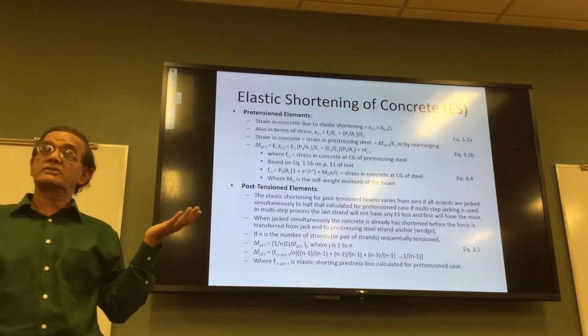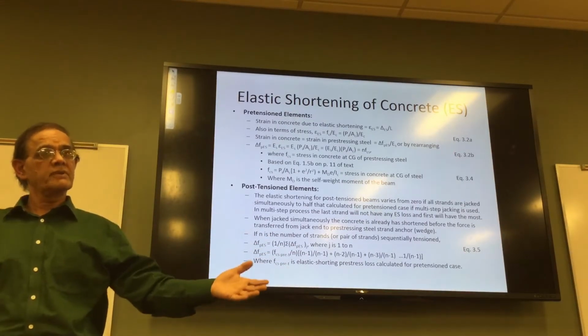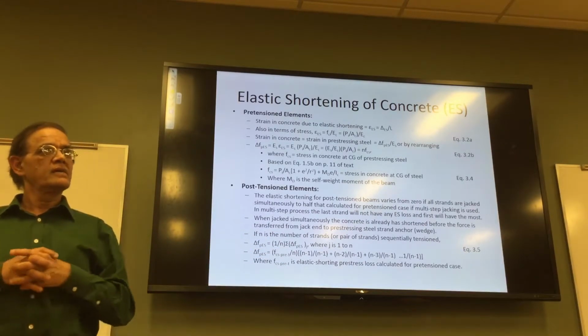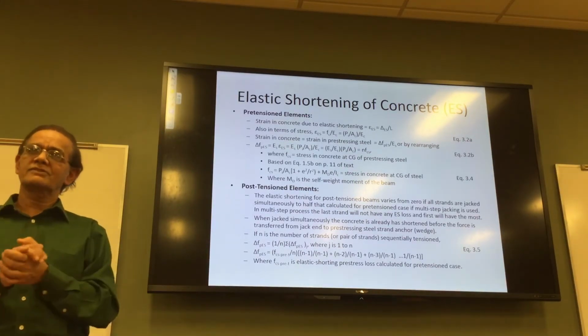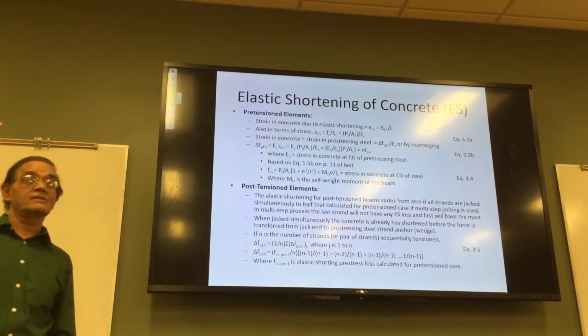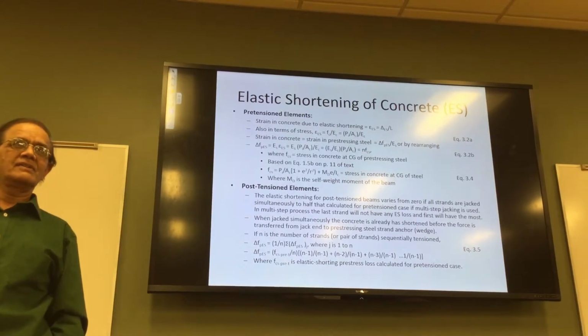The strain has to match, because their lengths are the same, the displacements are the same, so the strains are the same. So the stresses will be the same? No. Strains are the same, but the stresses will be different. Yes, because the elastic modulus is different, right?